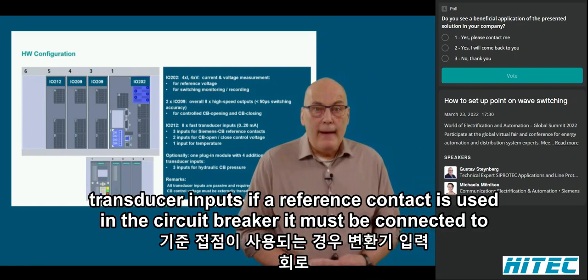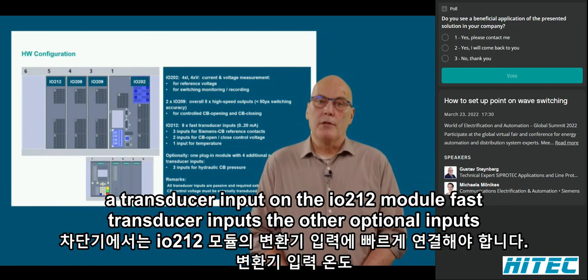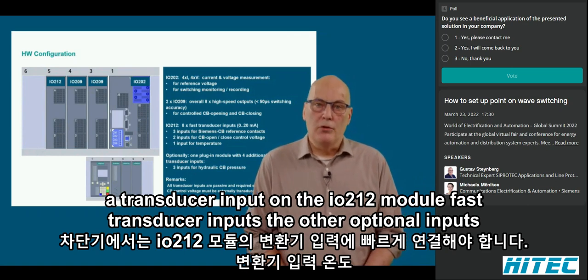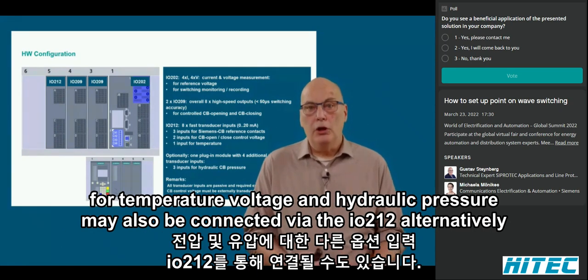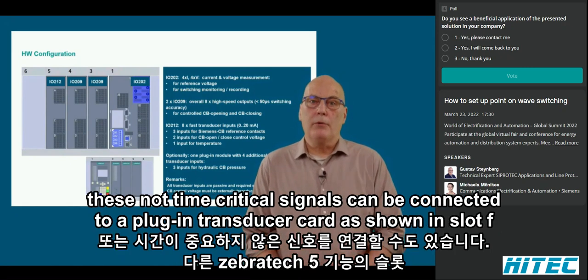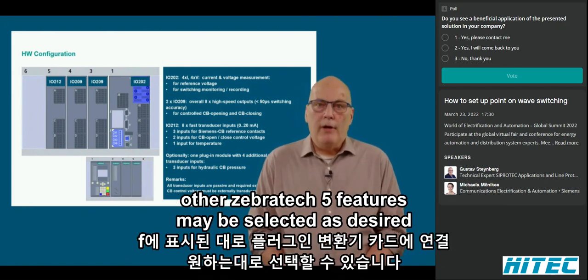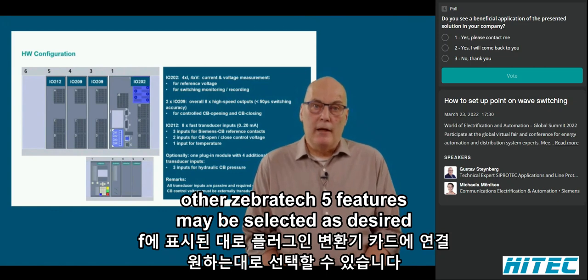Transducer inputs. If a reference contact is used in the circuit breaker, it must be connected to a transducer input on the IO212 module. Fast transducer inputs. The other optional inputs for temperature, voltage, and hydraulic pressure may also be connected via the IO212. Alternatively, these not time-critical signals can be connected to a plug-in transducer card as shown in slot F. Other SIPROTEC 5 features may be selected as desired.